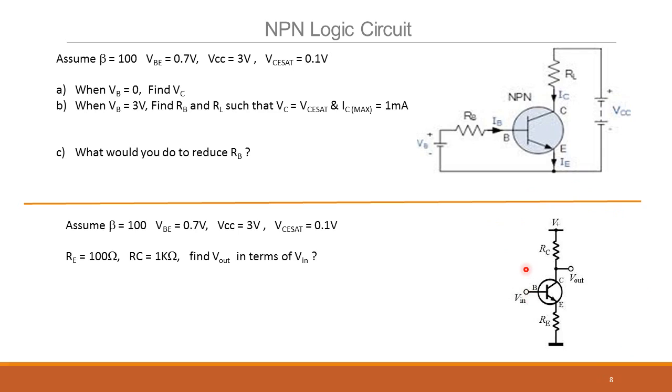You can see that if Vin actually increases slightly, you would expect that Vin is Vb, so VE will also tend to increase quite a bit. So the current through the resistor actually will increase because the other end is ground. So the emitter current increases, which means the collector current will increase. If the collector current increases, this voltage will drop because this voltage is fixed. The voltage drop across this will increase, so this voltage Vout will drop. So an increase in Vin is reducing the Vout. Right? So you get Vout by Vin as a negative quantity. It's actually a negative gain. Check this out. Once you understand that, you'll be able to do your circuits a little bit more easily.